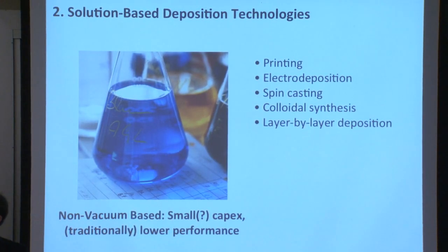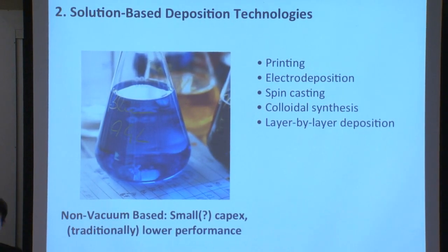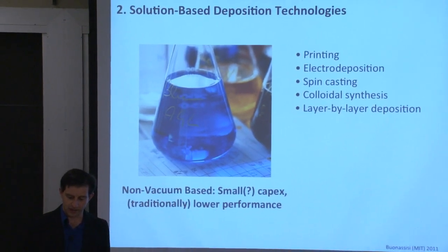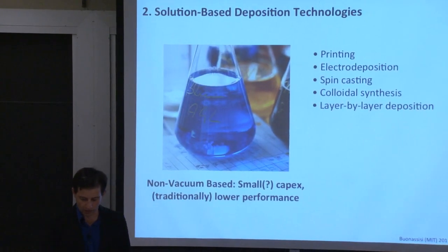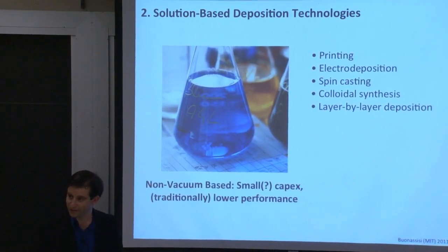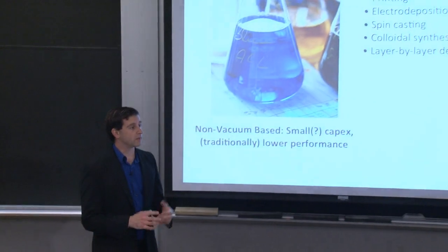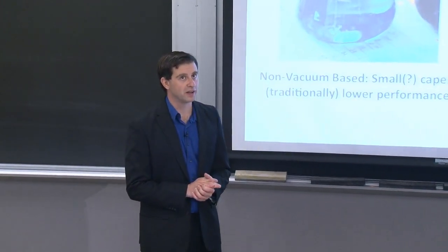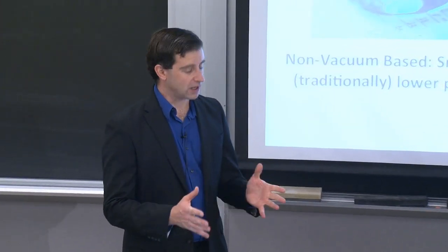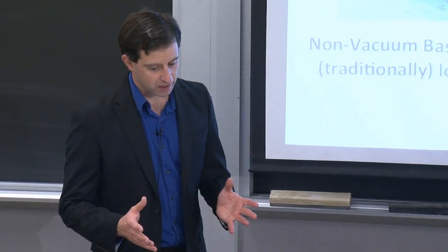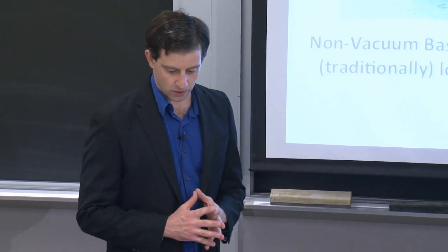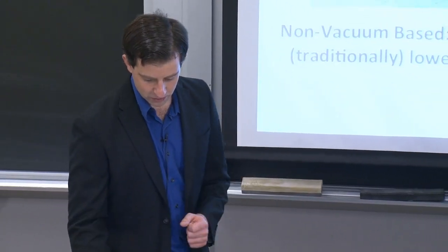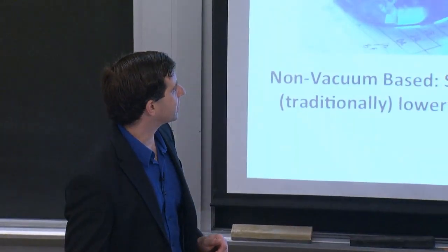Electrodeposition, on the other hand, is fairly well known. You're, again, applying a voltage difference between two electrodes, one of which will be your substrate, and depositing species contained within your electrolytic solution onto that substrate, growing your layers. Because you're growing at room temperature, these films tend to have rough surfaces. That could be a downside of electrodeposition. They might have some pinholes as well, but you do get fairly large-grained materials. It can be a very gentle growth process. And of course, the advantage is lower temperature. So you have a variety of different growth techniques.